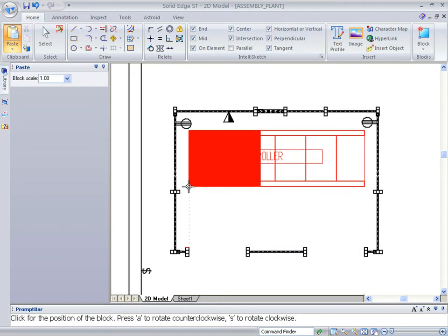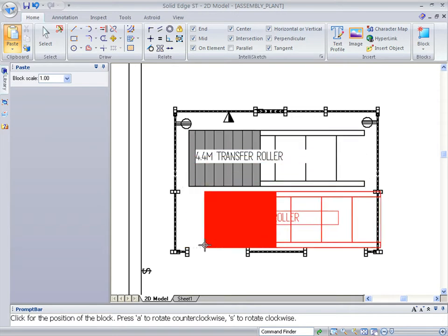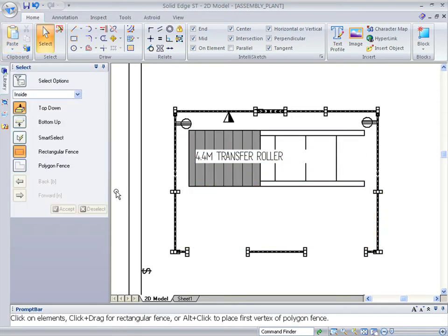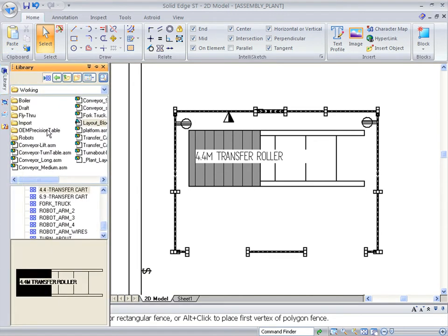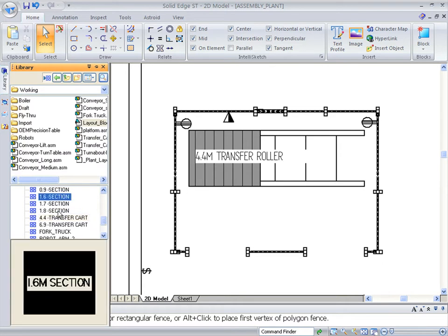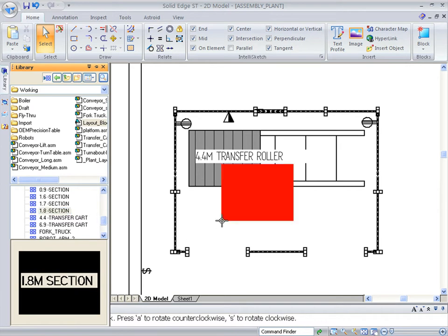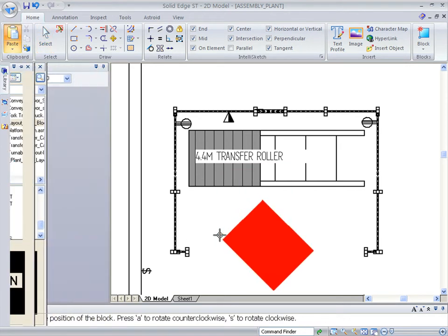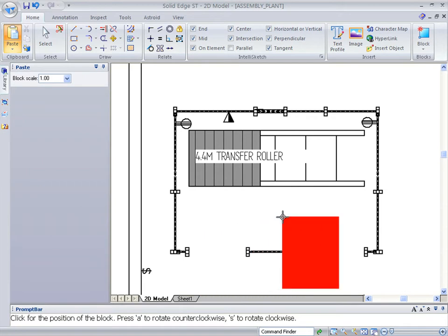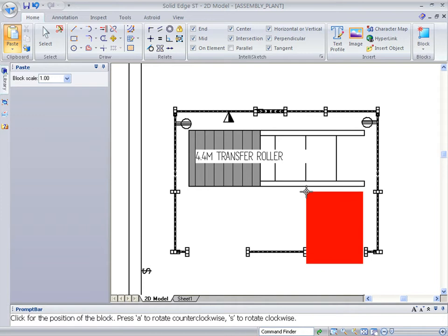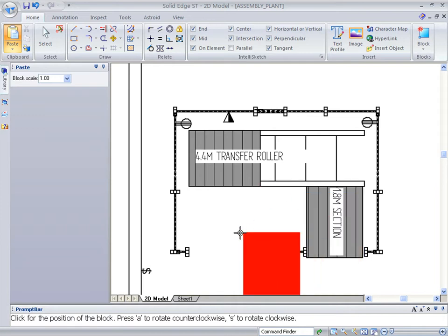Blocks can be dropped anywhere in the drawing and can be placed in precision by snapping to graphic key points such as endpoints, midpoints, centers, or aligned with any of these key points. The block attachment point to the cursor can be set by the user during the block creation. Once complete, the actual block displays with the appropriate color, hatching, line style, and so forth. Using the A and the S, we can rotate the blocks into position. And once again, picking up the endpoint of some existing lines, we can align and snap to specific edges.